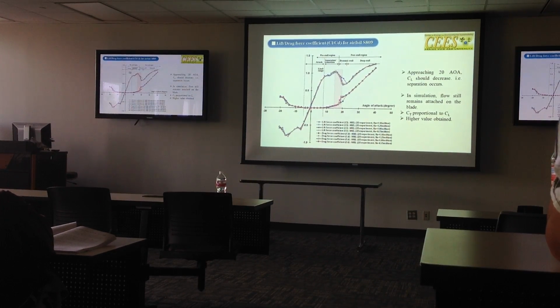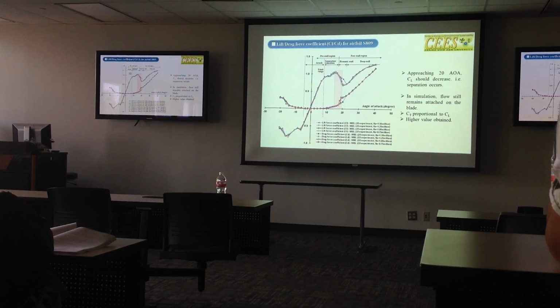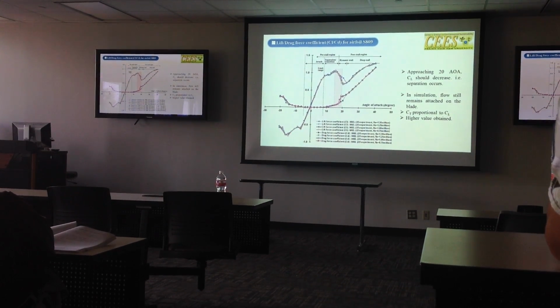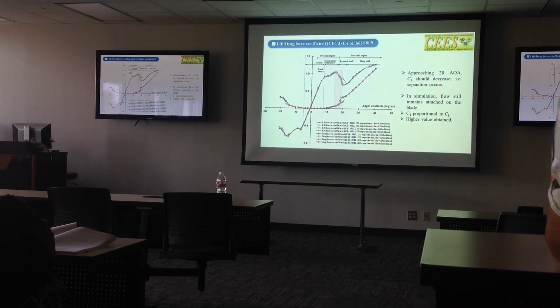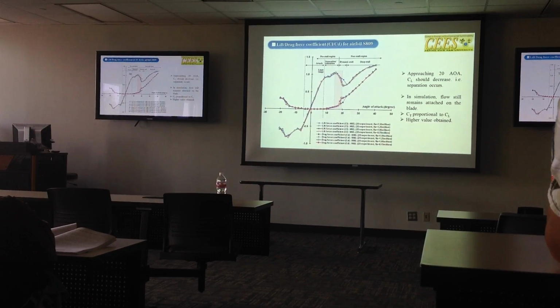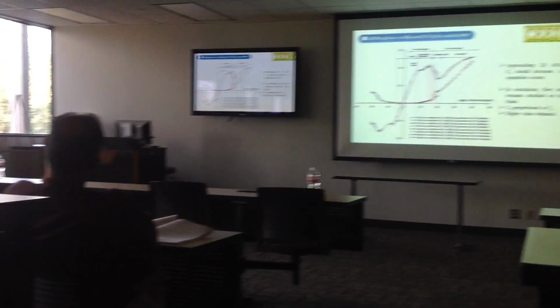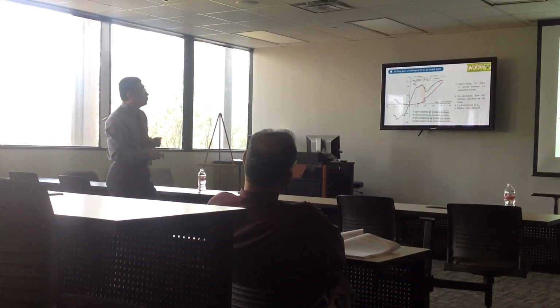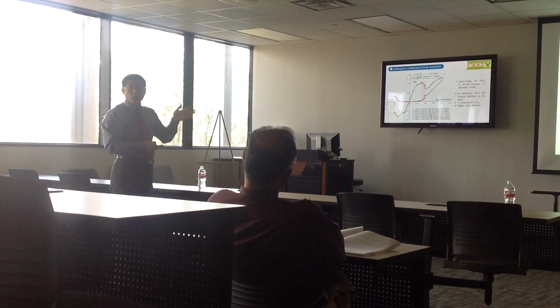And CT, the tangent force coefficient, is proportional to the lift force. Since the lift remains a little higher, CT in the simulation will keep a little higher value than the experimental data. That explains the higher value in the second section.